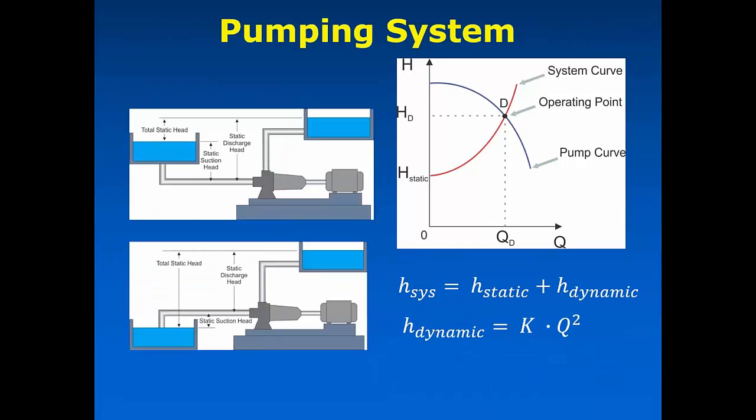Okay, so that's aeration. So now we're going to get on to the main topic of today, which is talking about pumping water. So the way that we've done this is that we've tried to allow people to specify pump curves for the various pumps that are being used in GPSX. And you can define a system curve as well, and that allows you to define the efficiency of your particular system. Are you having to throttle back? Are you wasting any potential energy here by defining those two particular things?